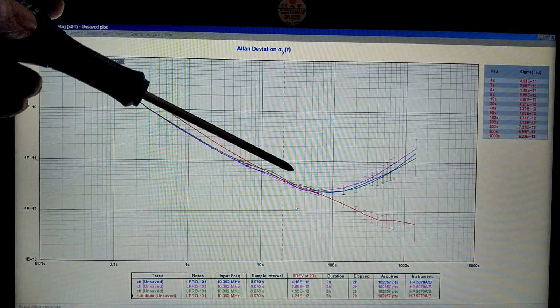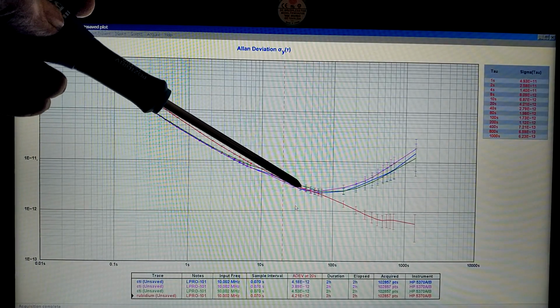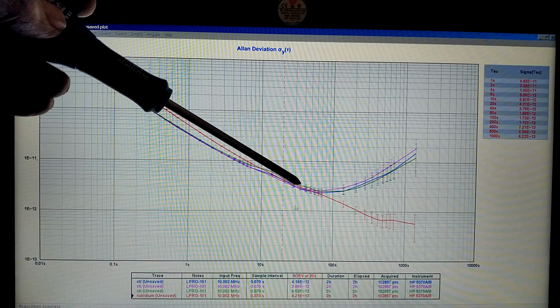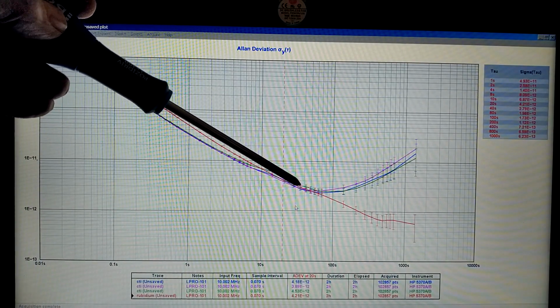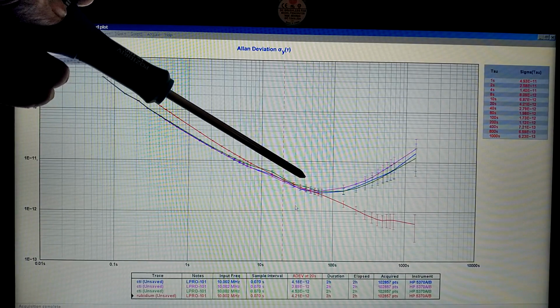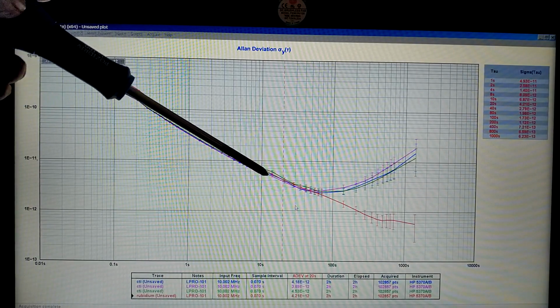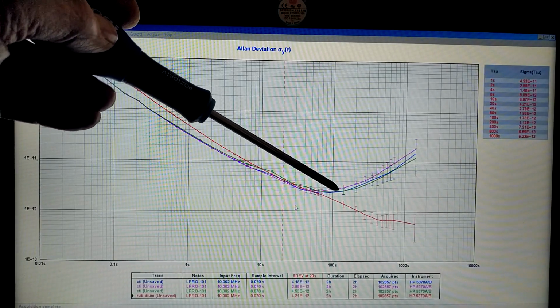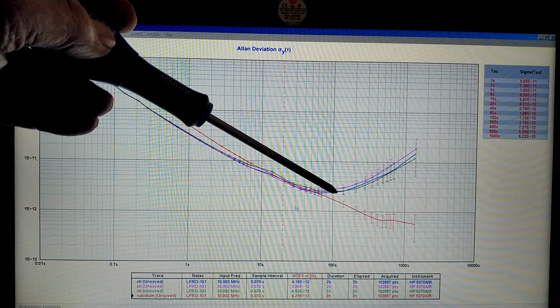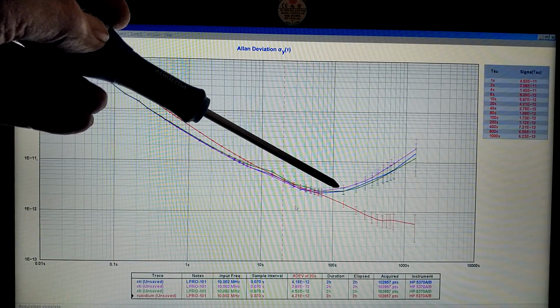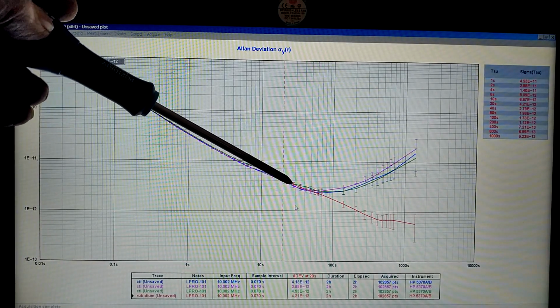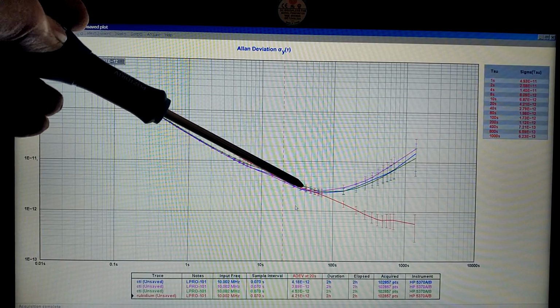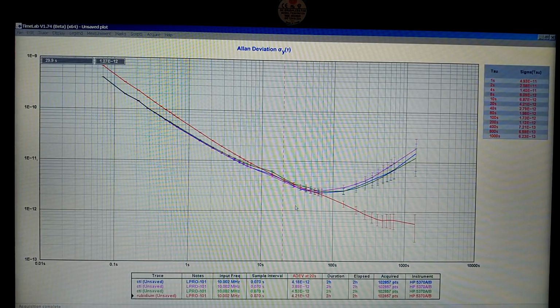Now, when I want to compare this with Linrad, I have the CTI still in the box, and I run a cable to the Linrad system. I can see that I cannot expect to see the noise from the CTI until I am above 100 seconds. But Linrad cannot measure above about 20 or maybe 50 seconds because it uses normal crystal oscillators, and one of them is not particularly good.